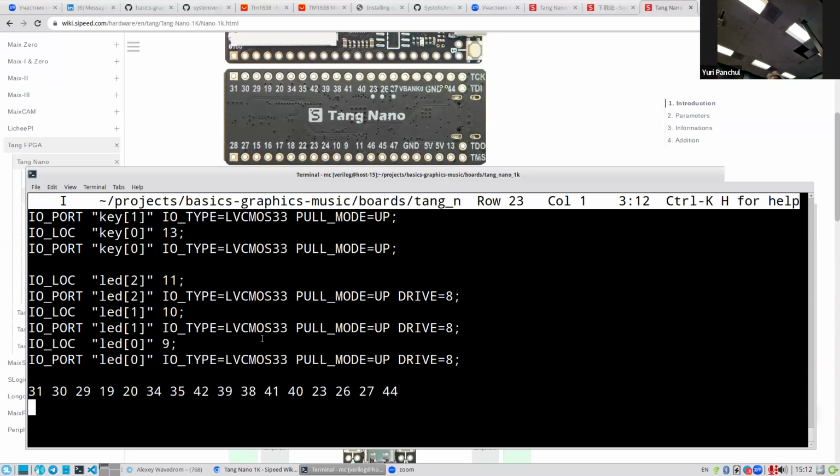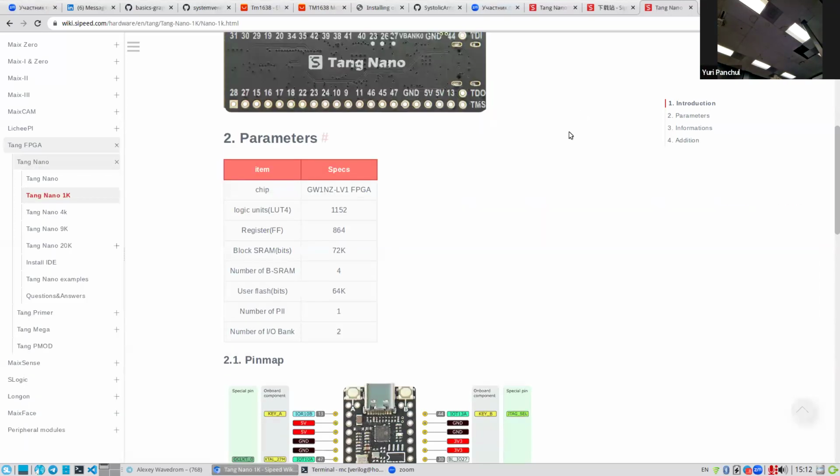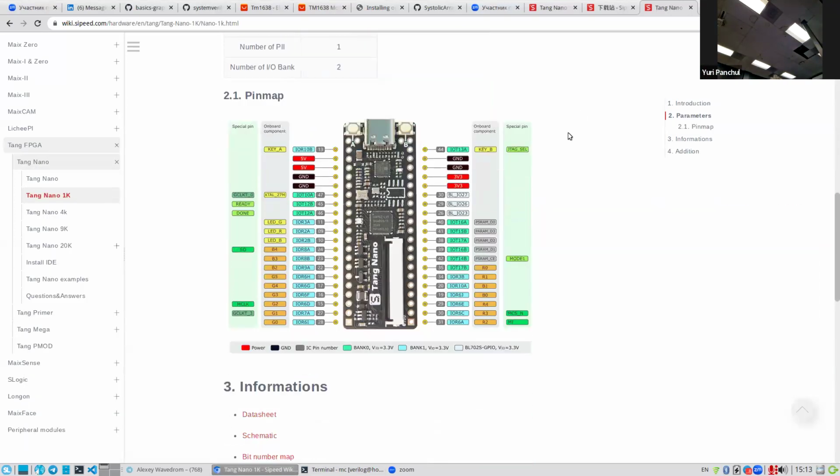Okay, next. Can we look at the next picture, the pin map? Is it okay that they do not correspond here? Here you see it's 29, and you said it's 27 on the board. That's weird. So there is some error somewhere. But this might be from a previous board, from a top down. So you need to look at this board.